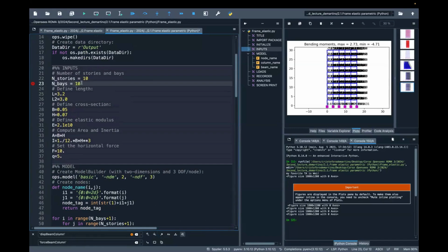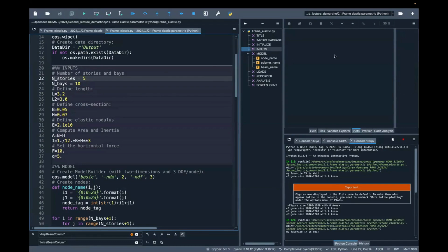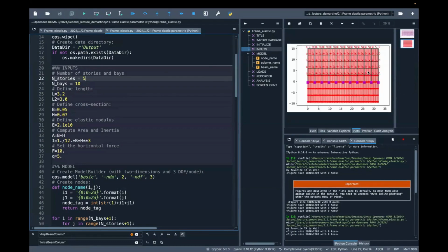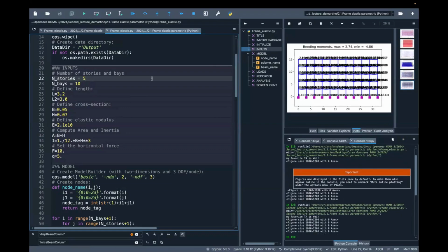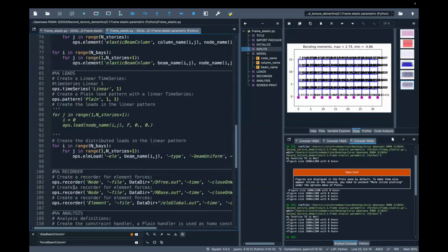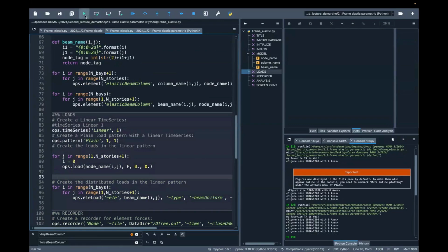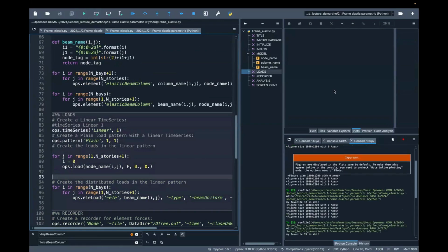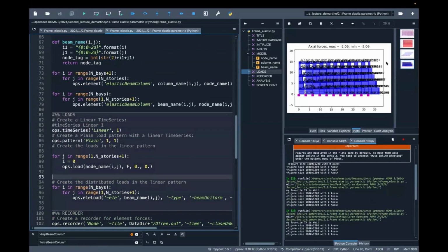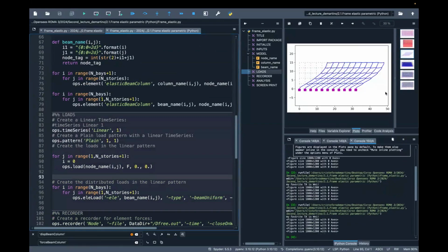You want to make a building in a different way. You can see here, for instance, we want to make a similar building but with 5 stories and so on, we can change it. If you want to apply forces to the same building at the same time, you can see horizontal forces and vertical forces. We can apply both together. Obviously, you can have a switch to make this automatic. In this case, the horizontal forces play a little bit more, you can see from the deformed shape. The deformed shape with this amplification factor is quite funny.